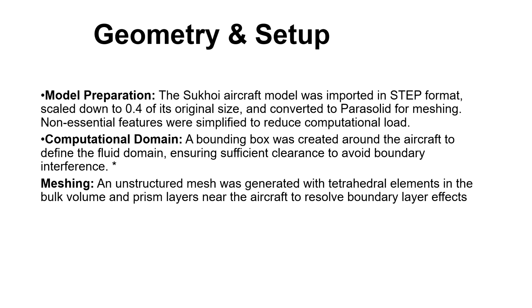For meshing, I applied an unstructured mesh with tetrahedral elements in the main volume and prism layers near the surface. The prism layers are important for capturing the boundary layer accurately, which directly affects the drag prediction.